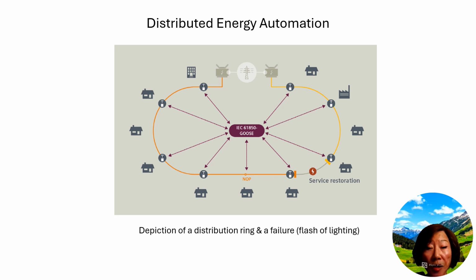Peer-to-peer communication is facilitated via IEC 61850 so-called GOOSE messages. GOOSE is an acronym for Generic Object-Oriented Substation Event, GOOSE messages, which provide data transmission as rapidly as possible using layer 2 multicast messages.